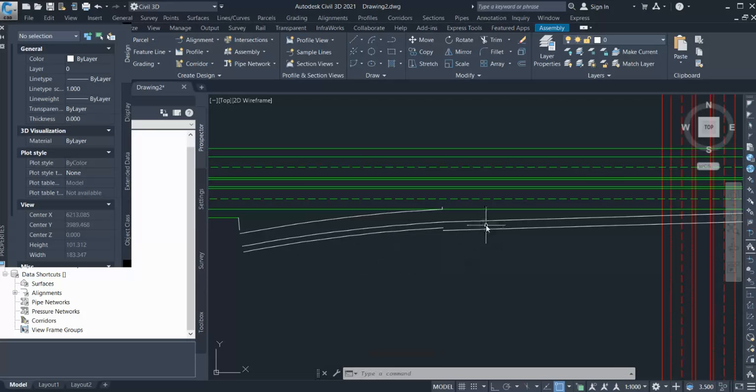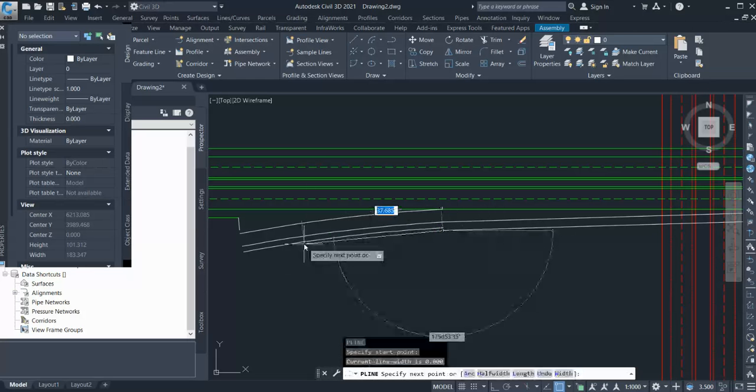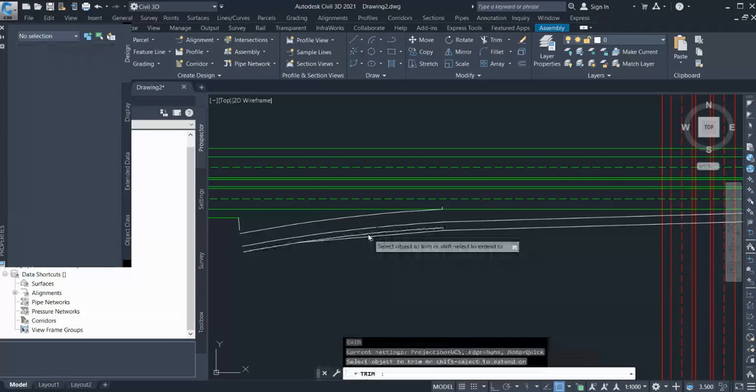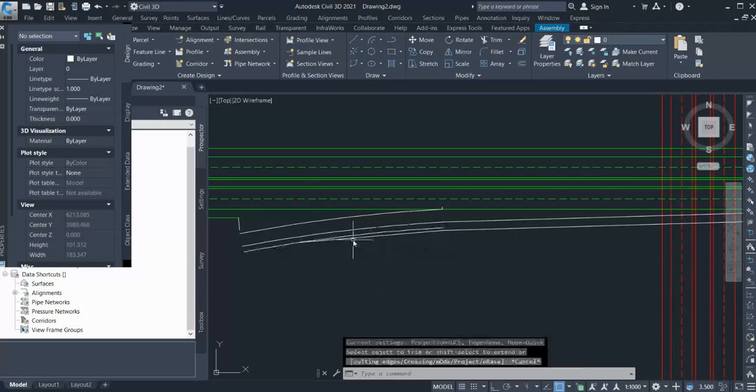So my hard shoulder 3 meter here and 2 meter here. So that tapering will be happening in this area, into the nose area. So you can go either with the smooth tapering. I'm just tapering here.